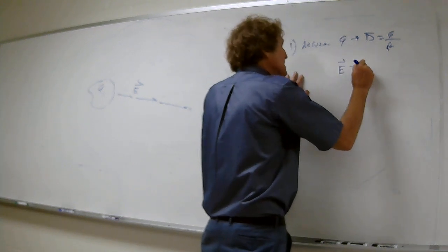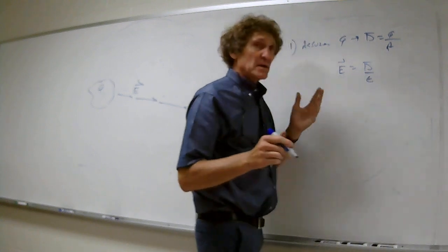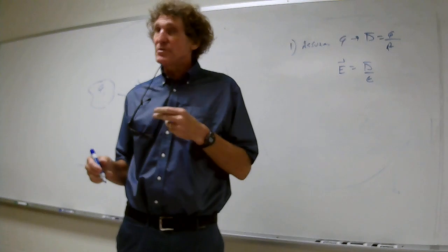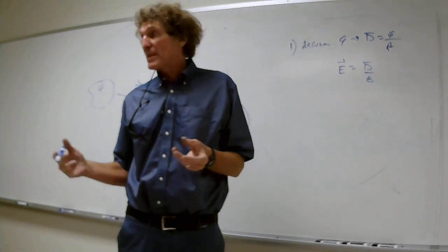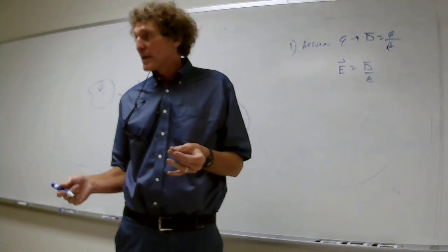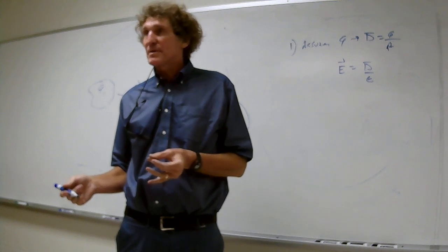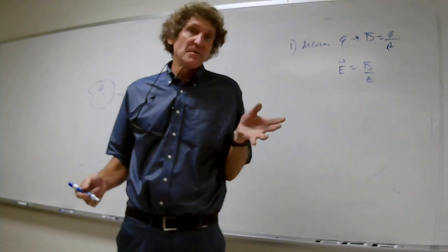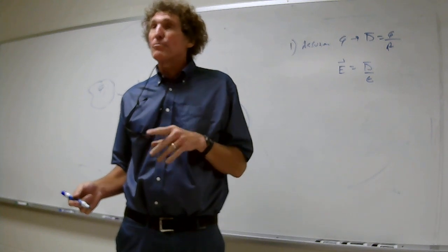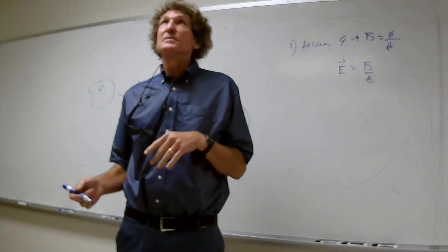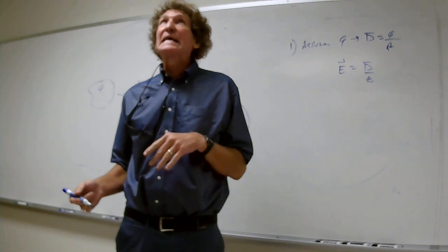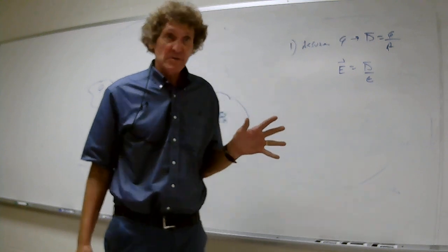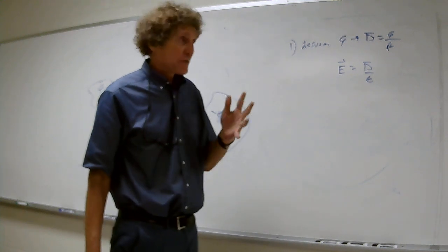E is simply equal to D divided by epsilon. That's all it is. And epsilon is the dielectric between the 2 conductors, usually epsilon relative times epsilon naught. That's the way it's normally rendered. You all with me? The book will talk about something called polarization, and polarization plus the D field gives the E field, and something called the susceptibility is epsilon relative minus 1, but don't worry about that. Just follow me right now. We'll use epsilon relative. It's more common than anything.